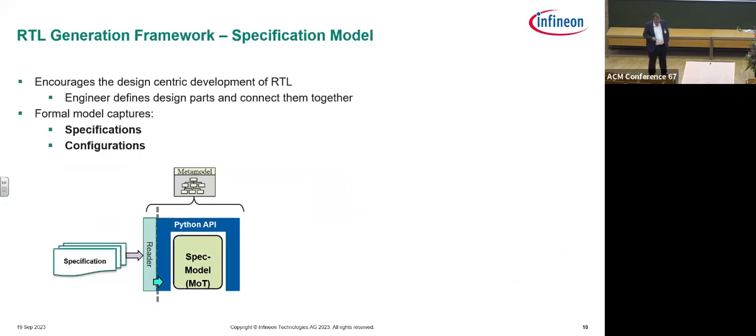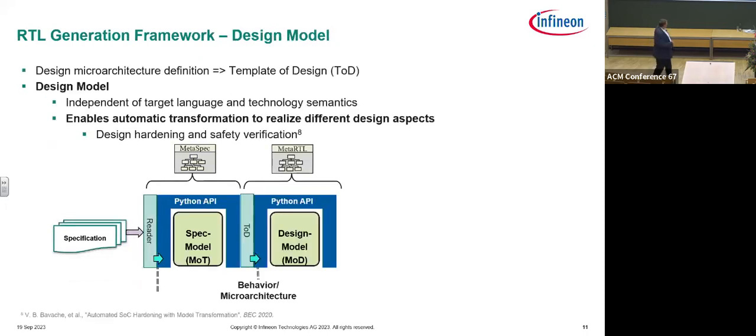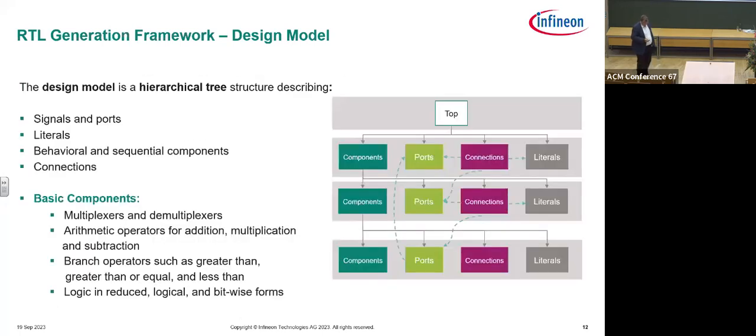This generation framework is based on a structured method from software called model-driven architecture. We have a specification in any form, XML, maybe text, whatever, and you have to extract information. When you translate your specification model to a design model, this design model, as I said, is an abstract RTL model. It has the classical things we have in RTL design: signals, ports, literals. So we have standard components in there, but also complex components, like decoder tables, like FIFOs.